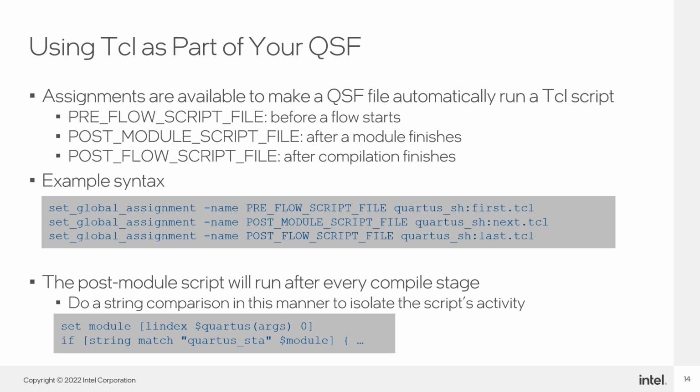The pre-flow script file assignment will run the assigned Tcl script before synthesis. The post-module script file will run the script after each compile step, and the post-flow script file will run the Tcl script after the fitter finishes.